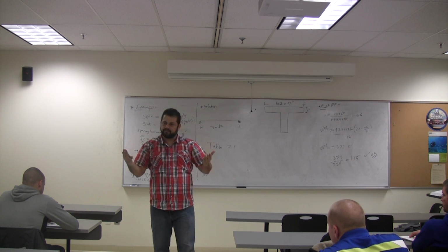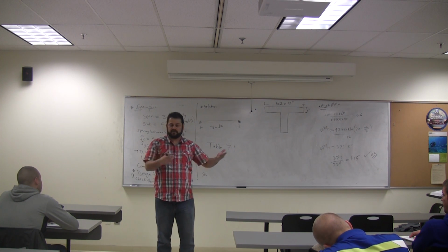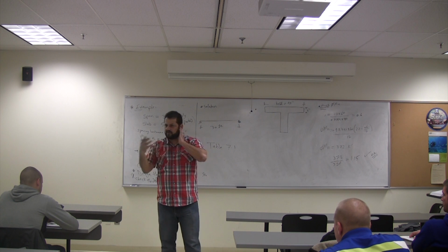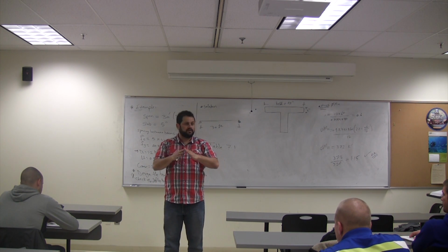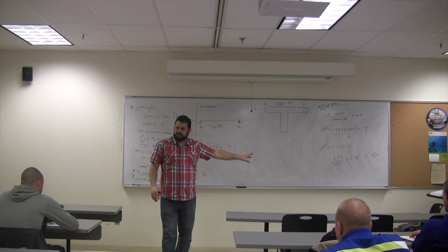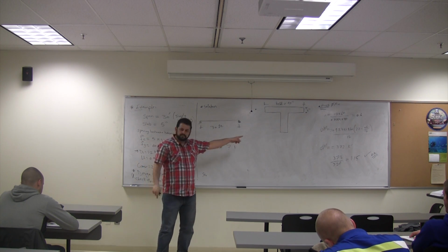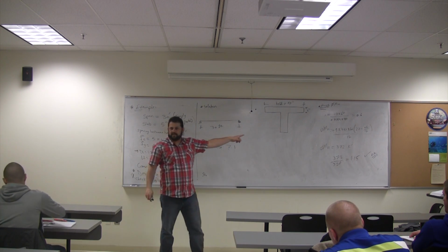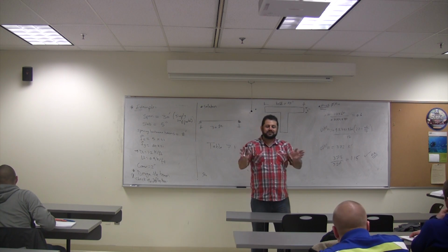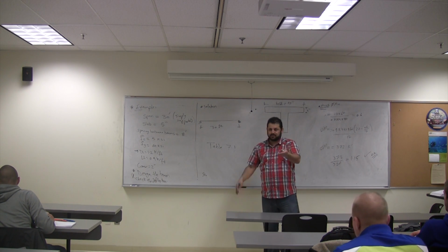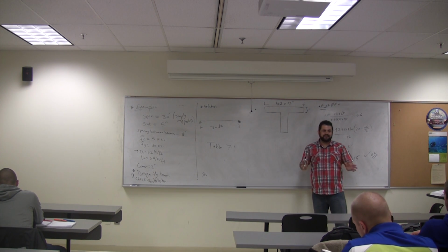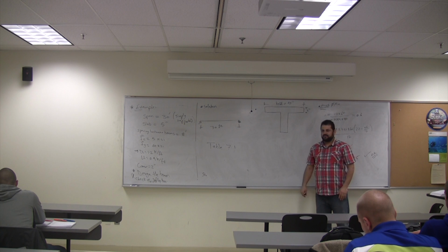So basically, if you have no limitation, and remember, there are other limitations if you have it outdoor or exposed to deicers, they may tell you the cover must be at least 2.5 inch or something like that. But 3 number 10 bars can fit within a 10 inch wide beam. By the way, there is a table, and I may show you later on. It tells you, based on the width, how many bars you can fit in there. There's one table in the design aids: how many bars you can fit in a given thickness, for each size.